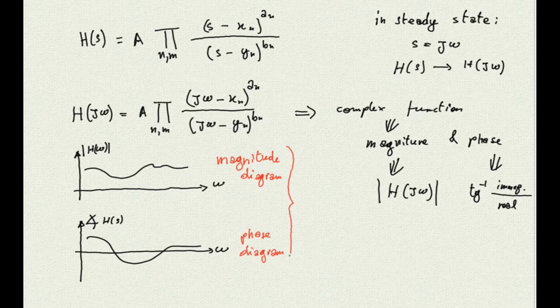From the second one, the phase diagram, we can identify the shift between the output signal and the input signal in a filter, depending again on the frequency. Do we need all the previous math to draw the Bode diagrams? No, at least not all of that. We just need some algebra to identify poles and zeros, and that's it. Once we do that, we can draw an approximation of the Bode diagrams with a simple graphical method, which I will now explain to you.